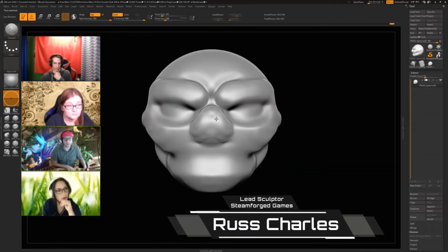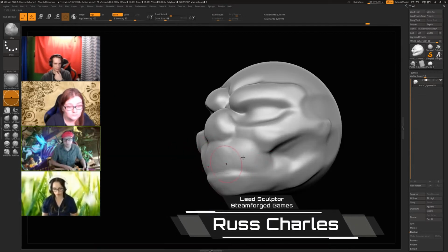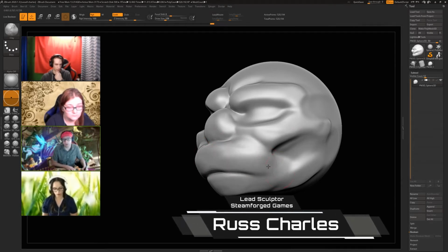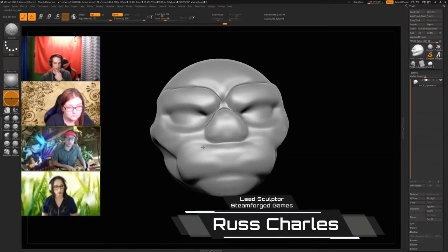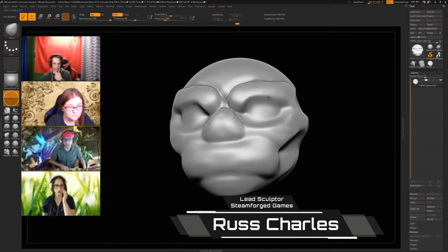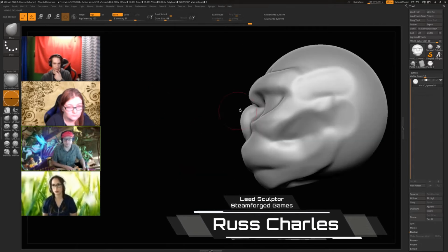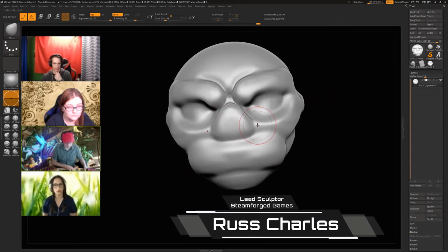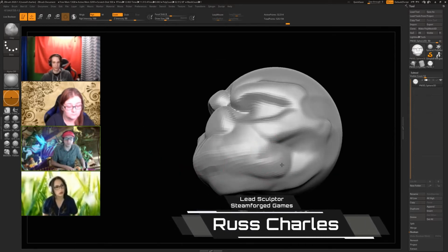But I find when I'm sculpting creatures or monsters that are fairly complex in their shape, like if we're doing a dragon or something, we'll get into the tens of millions of polygons in a program like ZBrush, and it'll totally support that level of detail. Whereas, as you know from working with your printer, you really want files that are in the tens of thousands of polygons. So there is a process that you go through that will allow you to reduce the polygon count afterwards without altering the detail, but it stops the model being editable.